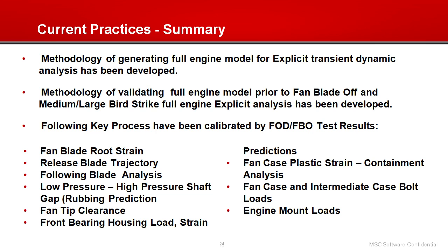Methodology for validating the full engine model prior to the fan blade out for different bird sizes has also been developed. Key processes for testing, like fan blade root strain, release blade trajectory, fan tip clearance, and engine mount loads, are all fully calibrated.